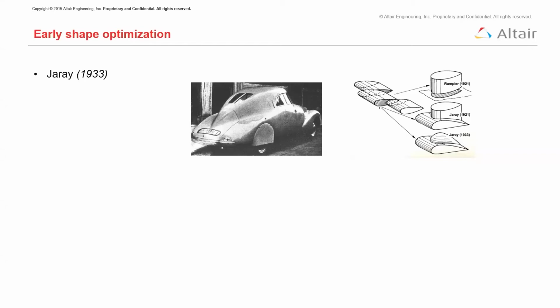By default, Virtual Wind Tunnel does a very good job of creating that mesh, that grid for you, the inflation layers, all of that, but it is fully customizable as well. And you'll see that part of that meshing, part of that prep comes before you even import it into Virtual Wind Tunnel. But yes, it is both automated and customizable. And you'll be showing some of that when you go into the tool. Yes, certainly.